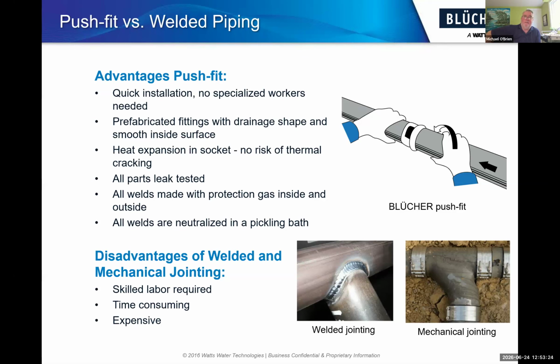It doesn't require specialized workers. All the fittings are prefabricated with the shape and a smooth inside surface. There's heat expansion in the socket, so there's no risk of thermal cracking. There's no need to design an expansion joint. Every single fitting gets leak tested at the factory before it's shipped out.